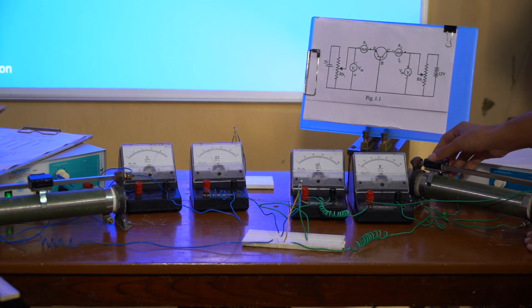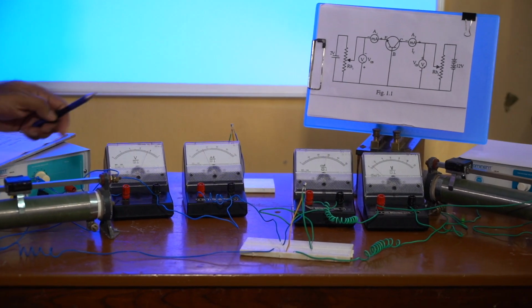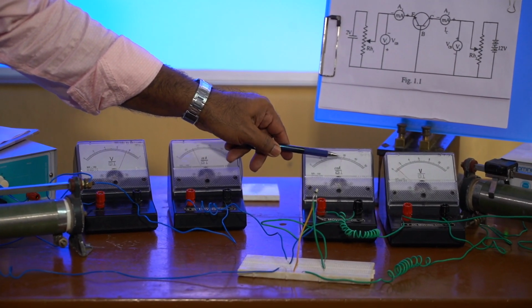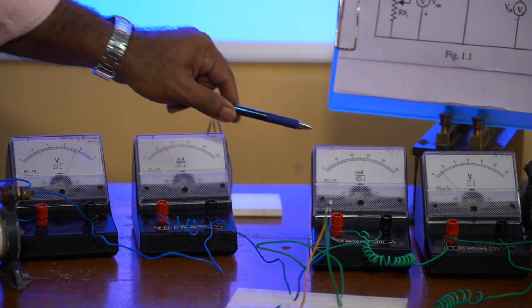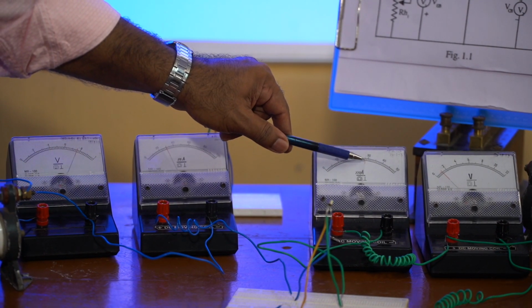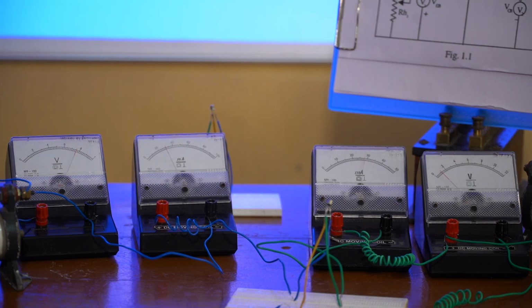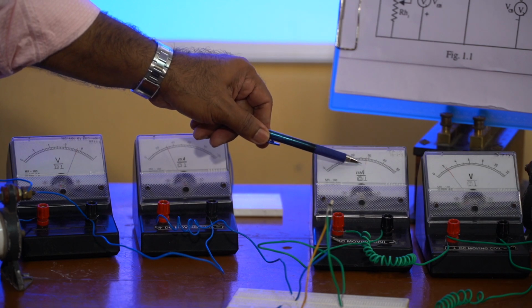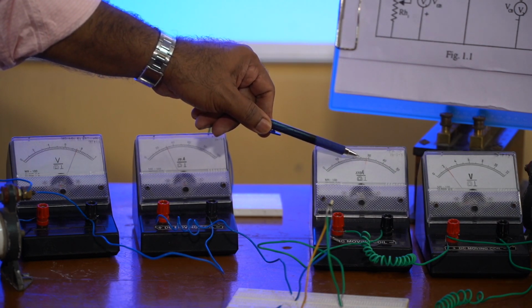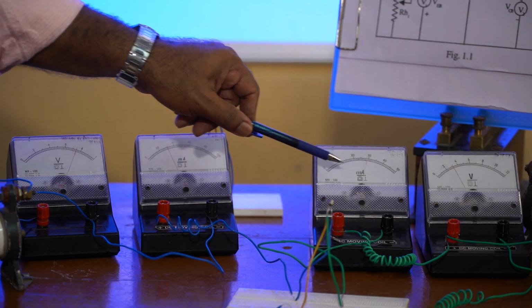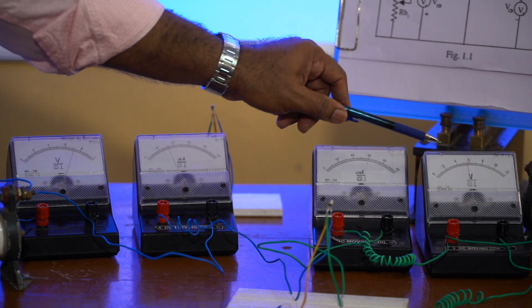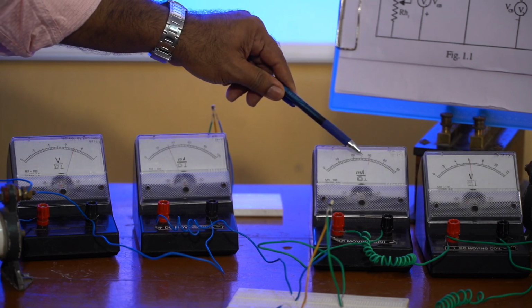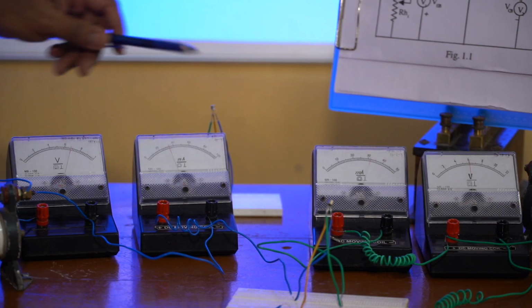Now, we change to 0.4. Now, it is again nearly 29. Then 1 volt. Now, it becomes almost 20 milliampere. That is the IC value. Now, 2 volt. Now, it becomes a constant here. It is not changing, that is 20 milliampere. 3 volt, again no change. 4 volt, no change. 5 volt, 6 volt, we are changing the value of VCB. Now, IC is remaining a constant, 6 volt, 7 volt, etc.